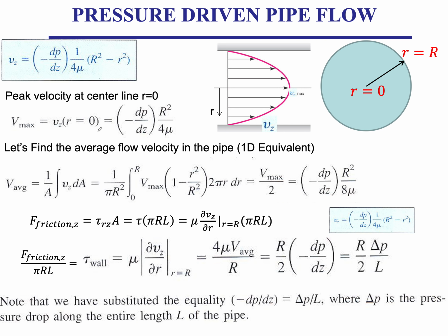This would actually be your maximum velocity. And if you want the mass flow rate, you just integrate the velocity over the area of the pipe. So you take a dA here, and the velocity perpendicular to the dA is Vz. So that's your dA, and that's Vz.